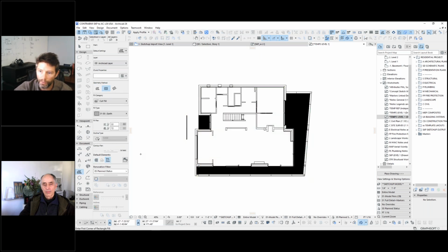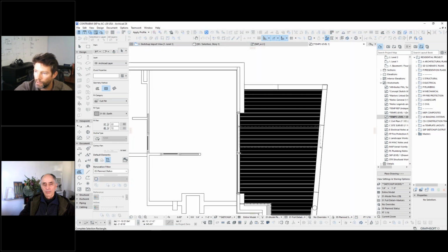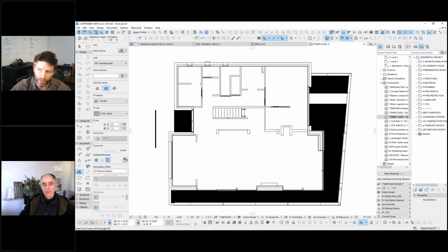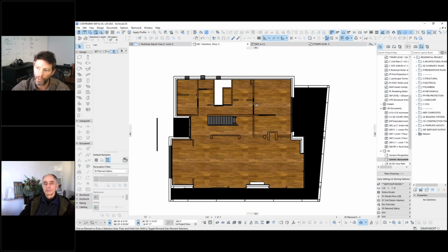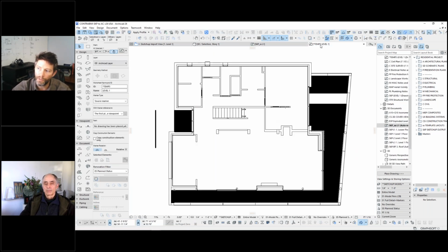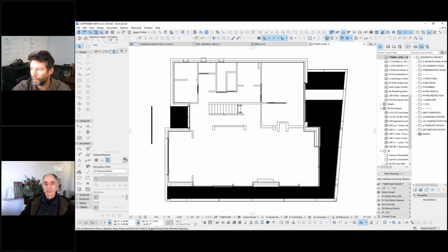So we can delete out all the fills, and we'd have to go in and selectively clear out some of these lines if we wanted to clean up the floor plan for use and reference. So that was the previous method of working from our 3D view to a 3D document, saving off a worksheet to ultimately use as a reference for rebuilding the project within ArchiCAD.